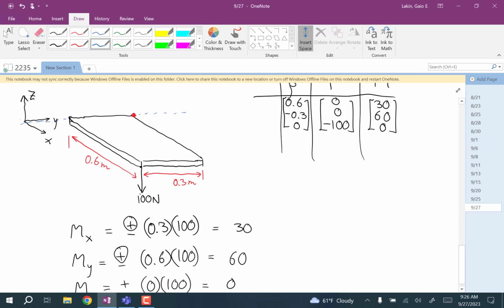And now think about the direction. This force would cause a rotation up the back, down the front. So do that with your fingers, up behind the axis, over, down the front. Your thumb's pointing that way, so that's a positive Y rotation. So the direction that your thumb faces when you're doing right hand rules will depend on